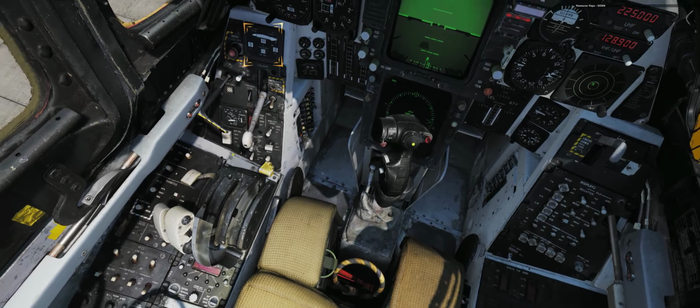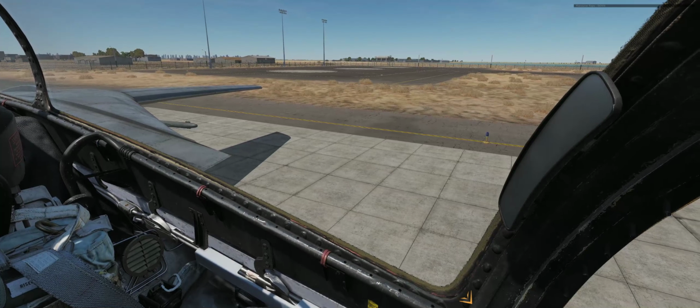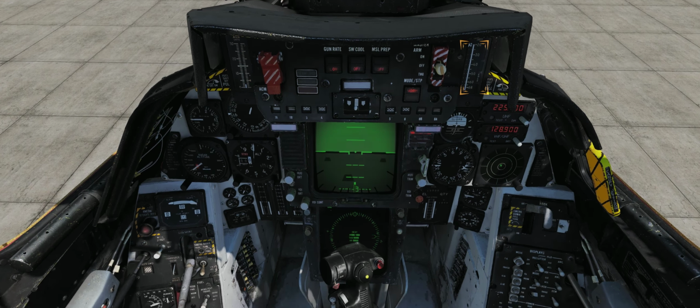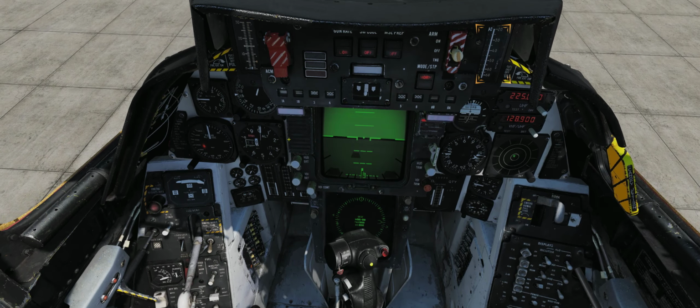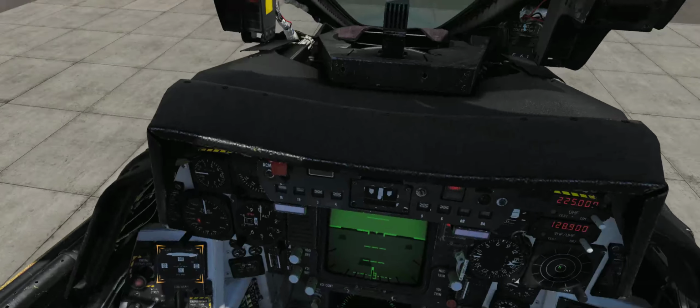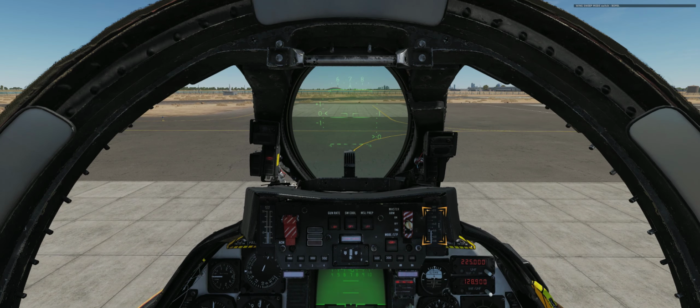Set maneuver flaps to down. Set wing sweep to 50 degrees using manual mode. Retract maneuver flaps. Set wing sweep mode to bomb and verify maneuver flap retraction.